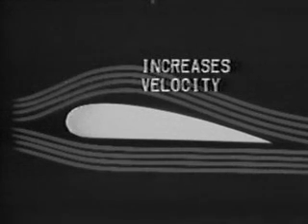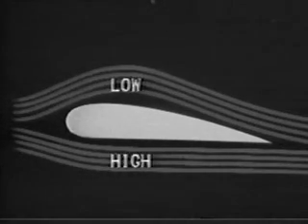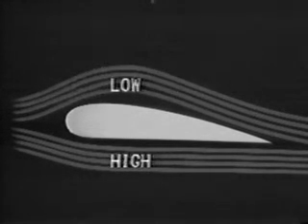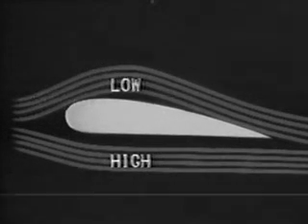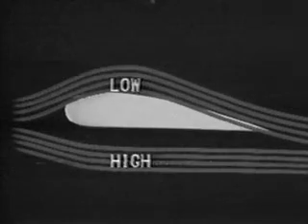You recall that when velocity increases, pressure drops. This is how a low pressure above the foil and higher pressure below is obtained. This difference in pressure creates a lifting force that pushes the airfoil towards the low pressure area.